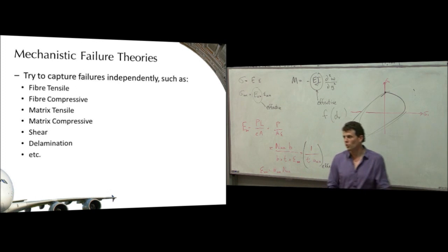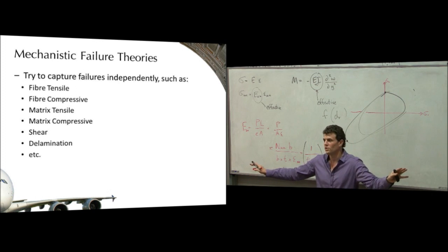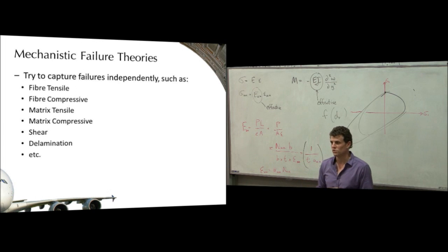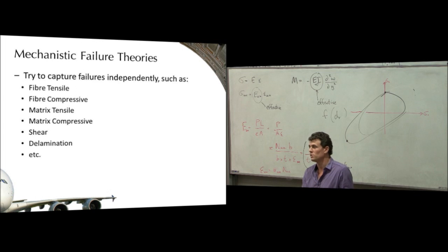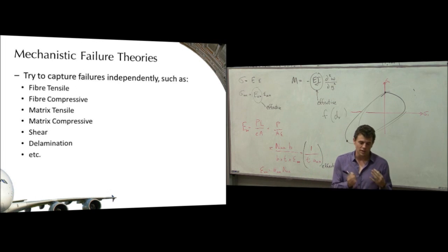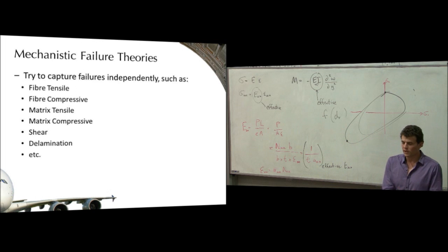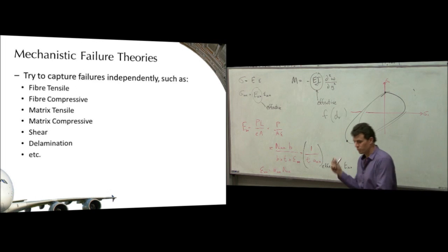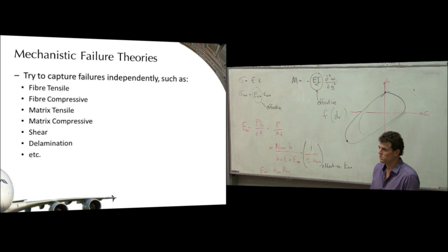and you've got a whole aircraft there, and you load that aircraft in a big fixture to test its ultimate wing load capacity and find cracking in the wing root. And then everyone freaks out and realizes that we have a multi-billion-dollar problem on our hands and have to go back to the drawing board and redesign whole components for the aircraft. So if you've got a better predictive capability, if you've got something that in a computer or on paper predicts failure more accurately, then you can save yourself very big dollars from a design phase later on down the track.